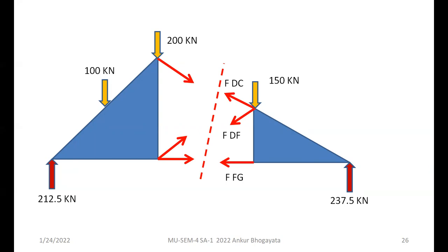You know what you need to do. You need to apply all the conditions simply one by one. In that process, do not forget to divide forces like FDC into components and FDF into components. So let me demonstrate it quickly for your reference. So I was discussing that this is the force to be divided into components, right? And this FDF will also get divided in two components.